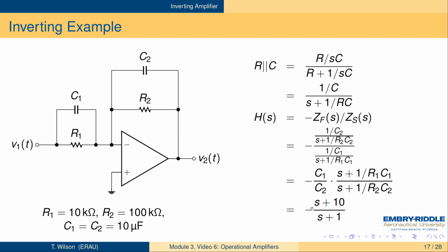Would that matter? If you're doing a single stage circuit, and if this input goes up, the output has to go up because you're controlling something, you're expecting an input that's say between 0 and 10, and this is between 0 and 5, then you've got to do something to invert that again by making another inverting amplifier with a gain of -1 to get rid of the minus sign. If it's sinusoids and you don't care about the phase, then this is going to have the same frequency response, the same sinusoidal steady state responses as the previous circuit, and so it doesn't matter. So we get to the issue of design considerations and constraints external to the design that are going to determine which kind of circuit we use.